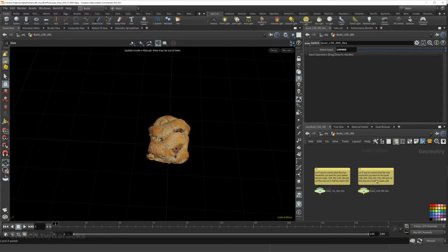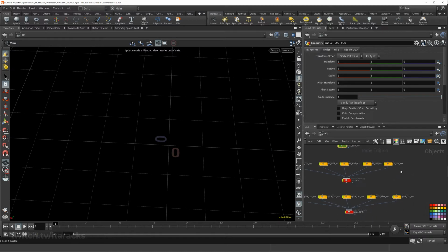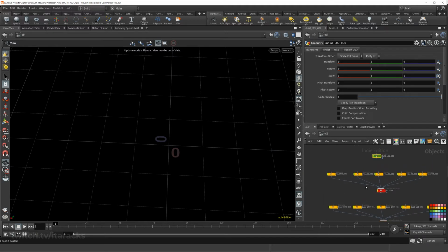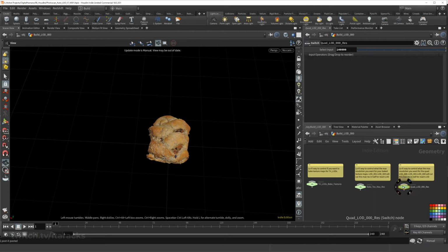This also notes that from level of detail 1 through 4, it is progressively decreased just based on a good flow that gets down to similarly and matches what's happening in the tri-level of detail. So the level of detail 4's amount of polygons will match quad level of detail 4's polygons roughly. So that's just a way of updating that. So if you want the quads to have more or less, you can update that here as well, and that will propagate against all of the other quad meshes.